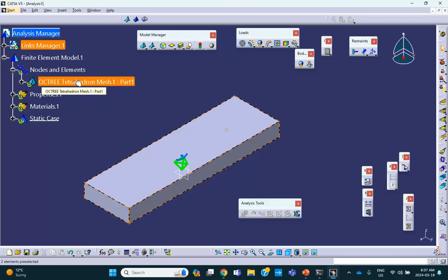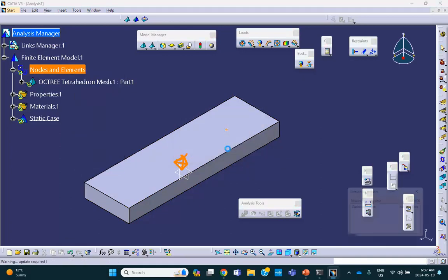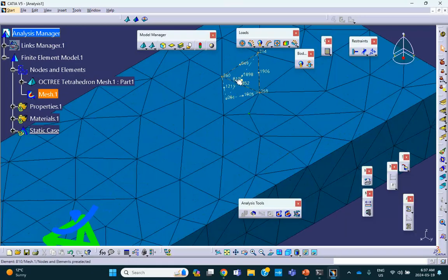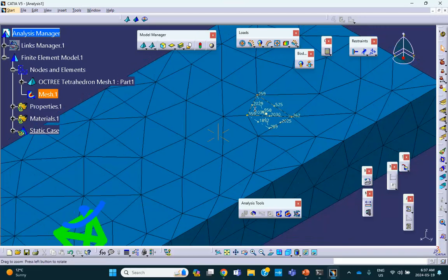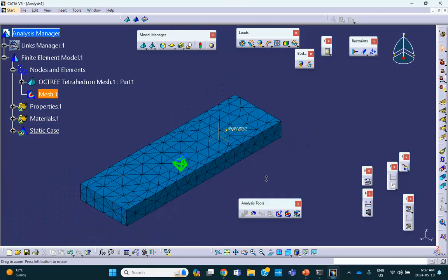So if you right click mesh visualization, you see this right there, that's guaranteed. And because of that, when you put a force here, it's actually transferred to the information around it. Without that, this point is going to be somewhere in the middle, and you put a load there, it doesn't know what to do. Okay, deactivate this.